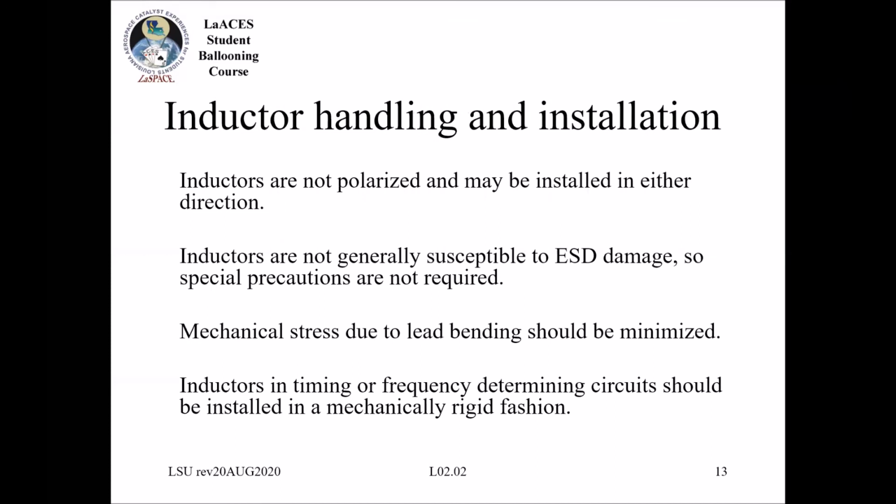So the handling and installation: they're not polarized and may be installed in either direction, but I was certainly working with some of these PCB mounted ones from Coilcraft for particular filtering, and they had a recommended orientation. So just because they're not polarized, there might be a preferred direction. Again, look at the data sheet, get with the vendor and find out.